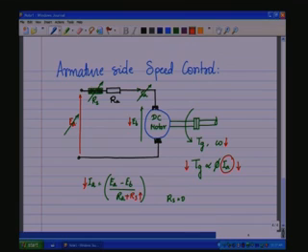So, now EA minus EB is going to get distributed between RS and RA in the ratio of their values. In this way the speed can be controlled either by controlling the armature voltage or by controlling the armature current by way of a series resistance or rheostat connected in series with the armature.